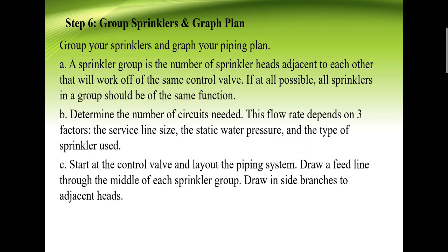For example, each bubbler should be grouped together, starting at the end of each particular sprinkler group and working towards its control valve, noting the number of sprinkler heads. If you have 3 valves, you will have 3 groups of sprinklers.